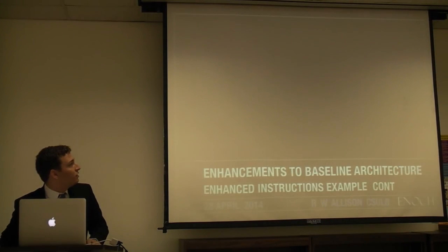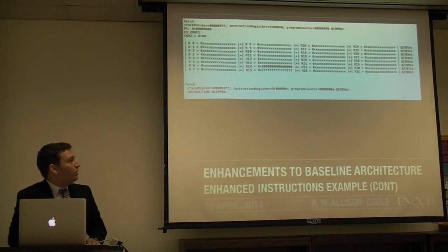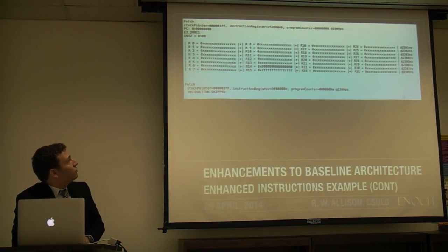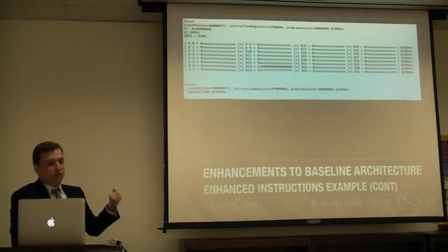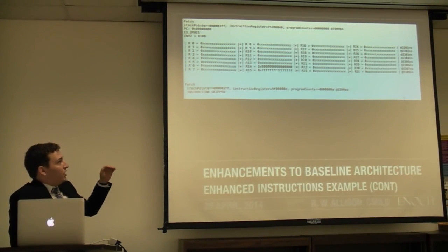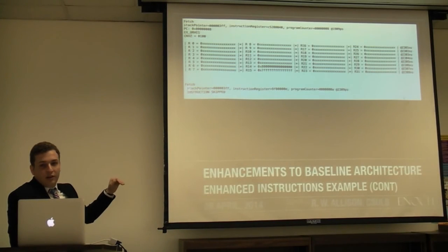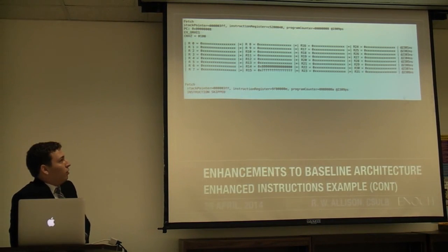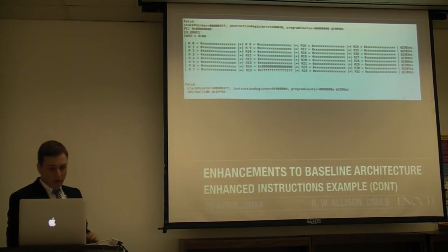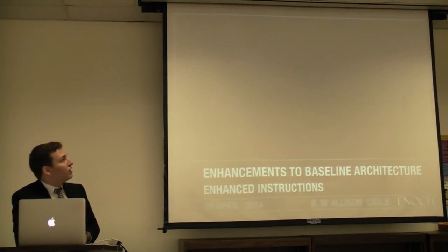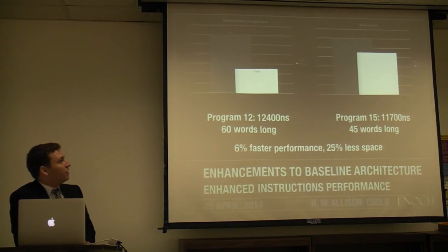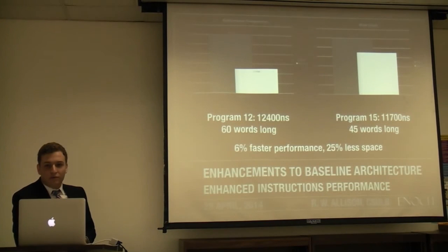And what this actually does for us, like I said, when the program is actually ran, it goes to fetch, executes previous instruction, and then once it reaches fetch again, it skips the instruction without getting to execute. So our execution block for what was a halt was entirely skipped, thus saving 1 clock cycle. But what actually happens when using our enhanced compiler, or a compiler for our enhanced instruction set, is that your program is much more efficient.